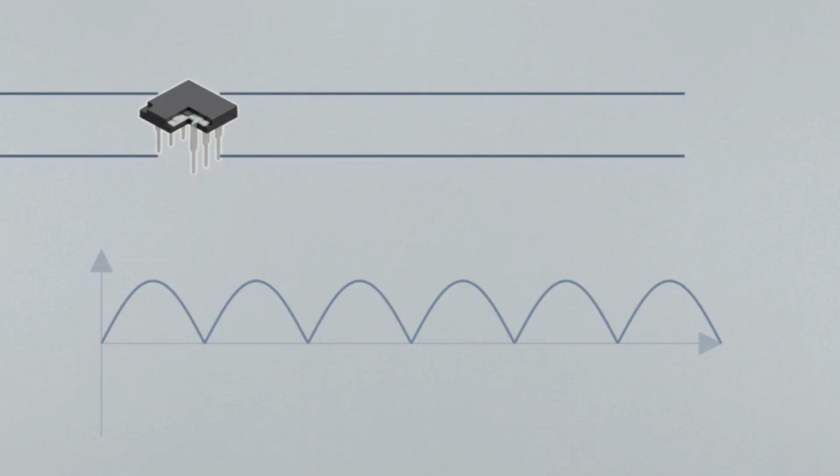But the rectifier's output is highly flawed. It produces a series of sharp, pulsating peaks, separated by deep voltage gaps. Every time the wave drops into these troughs, the voltage falls completely back to zero. An unprotected logic circuit connected to this supply would rapidly flash on and off.